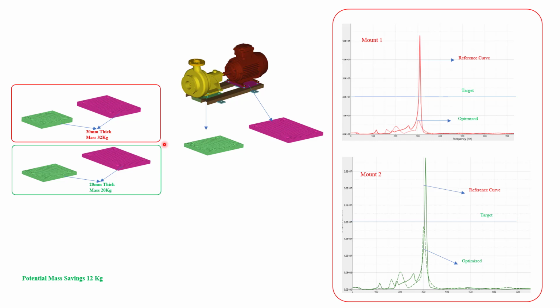Yeah. So next, I could see the same for mount 2 also at around 310 Hertz. The peak got reduced. The peak is drastically decreased. You could see at 310 Hertz, I have a least 5 e raised to 6, and this peak got slightly shifted to around 300 Hertz, which is below the imaginary target which I had considered, 2 e raised to 7.